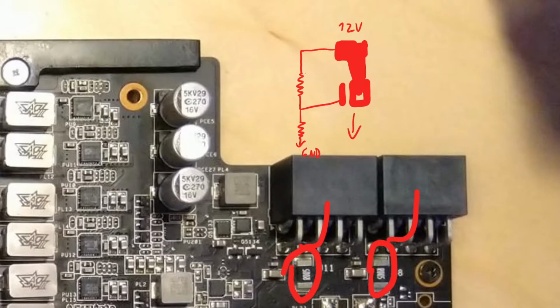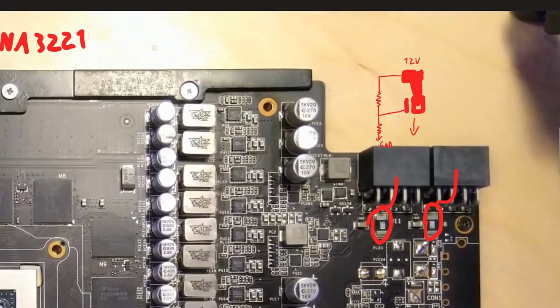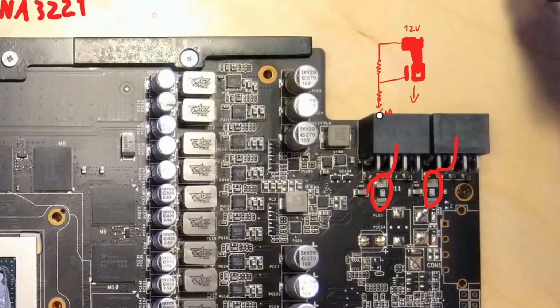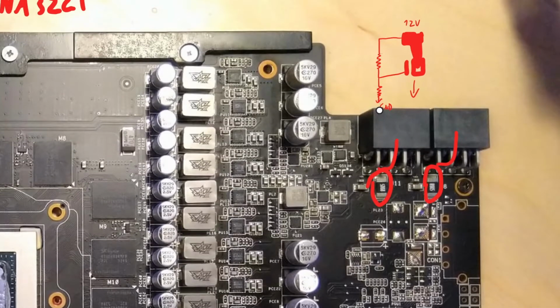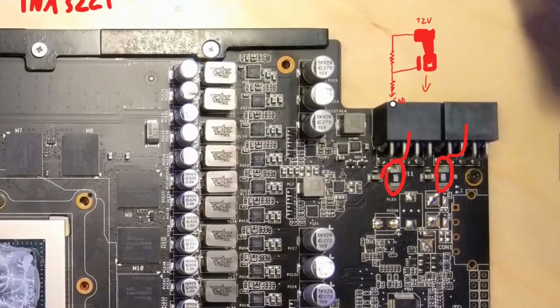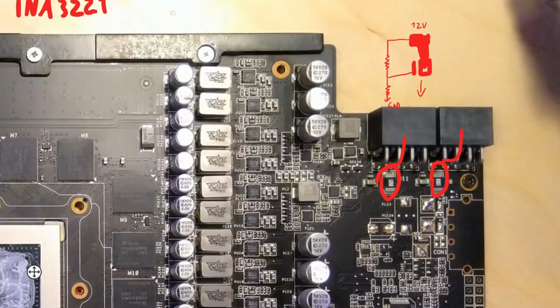Because now the reading won't change anymore. Because before, if you pull more current, like if the card suddenly pulls more power, there's more current going through the shunt, therefore the voltage difference changes, therefore the INA3221 sees we just had our power consumption change. If you do it like this, if the power no longer goes through the sense pad on the output, the reading won't change with changing power consumption anymore.